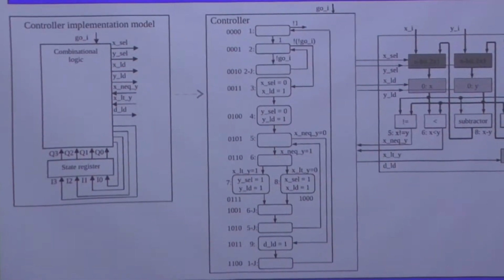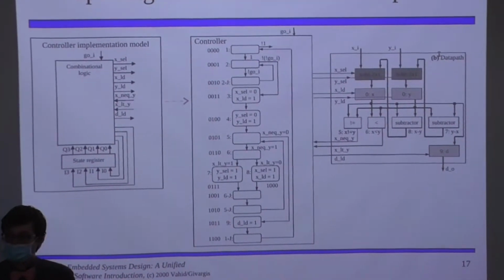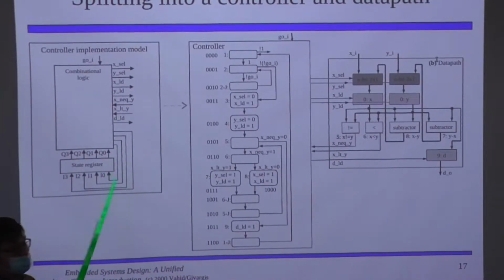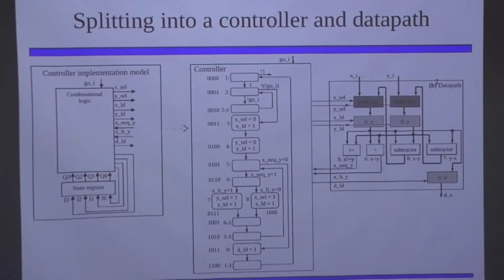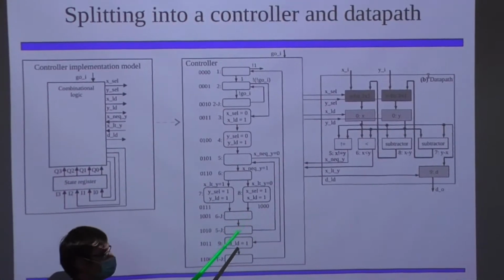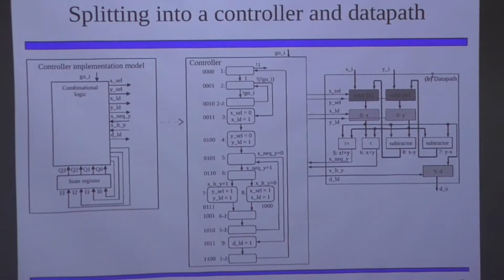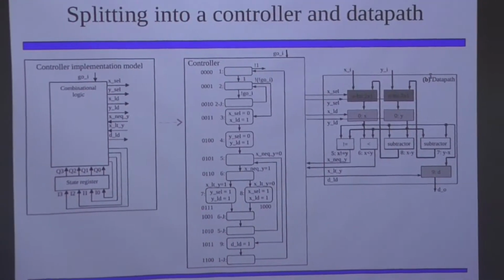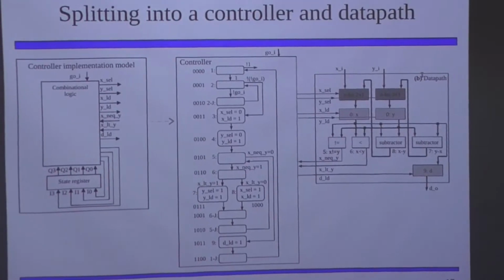It's 8, pardon me. So if we take a look, those correspond to the state panels in which those operations occur, right? With register load operations, it's correct to assume 1 when you're loading and 0 at all other times. This isn't a situation where you have a don't care value. If you were to put a don't care value wherever y load is not being set to 1, then a don't care value basically says you could be loading, you could not be loading, I don't care. In this case, we definitely care. We want to make sure that we're not loading anything into the register at times other than those specified by the diagram. So 1 when loading, 0 otherwise.